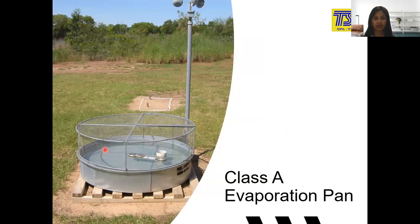And this one is the class A evaporation pan, which is located on the ground. This is the wooden frame, and this is the measuring device. And this is the filter area to prevent something from going inside the evaporation pan. Because as you know, this evaporation pan is located in a widely open area, and there will also be wild animals in this area, for example birds, and they can disturb this evaporation pan. That's why it uses this filter or screen to prevent that from happening.